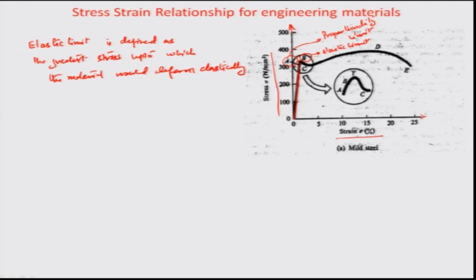So, beyond this E b, the strain that is recorded as E b here, the stress value drops suddenly, as you can see. Any further strain increase beyond b registers a drop in the stress value. That is why the curve is dropping down here. So, for any further deformation, the material does not resist as much as it was resisting up till the elastic limit. Okay. So, this is supposed to be the yield of the material.